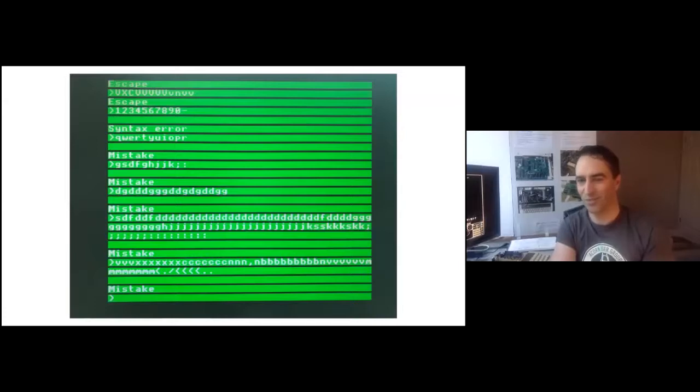How the Electron's keyboard works is like most keyboards, it's open collector. So there's some 33K pull-ups, which result in the lines reading high when no keys are pressed, and when you press a key, one of the lines goes low. Except a 33K pull-up versus a 5K bus hold resulted in a very slow or non-existent high level on the pin. So some keys kind of worked, most keys read as something else. It was obvious the keyboard was sort of working, but just not very well.